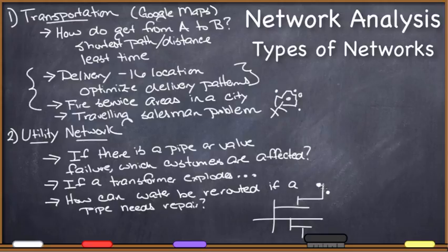And so you go, okay, I've got these two people who called in who said they don't have water or power. Could the problem be here? Okay, but then this person calls in and go, okay, well now it can't be here. It's got to be further up this network because this person called in here. And then this person calls in over here, and you start to get these people calling in, and you identify that, oh, but nobody calls in from over here, so we must have a problem here at this juncture.